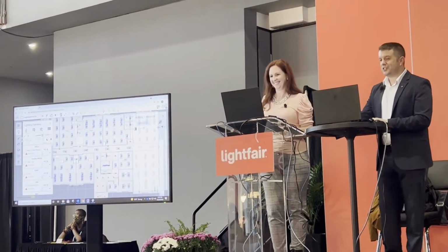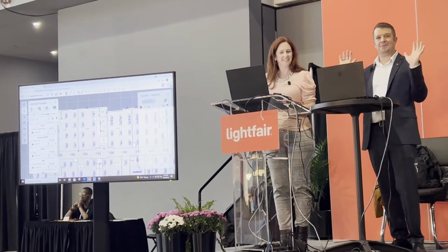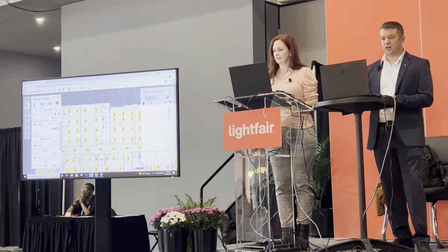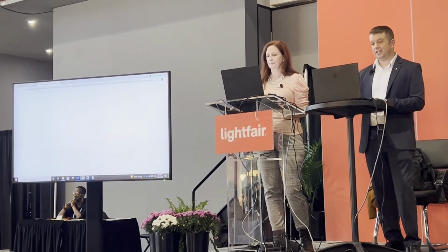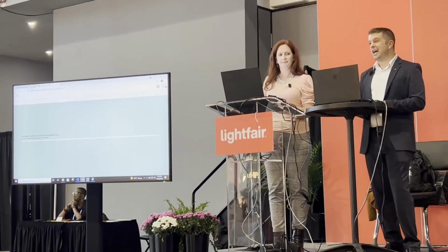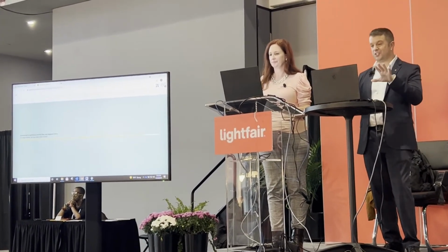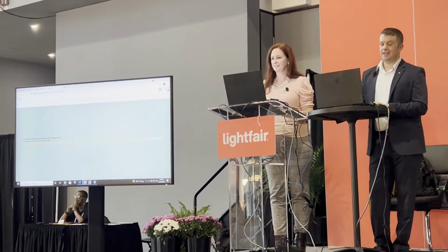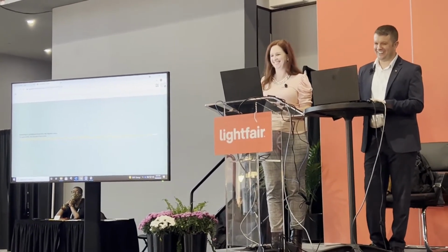So if you look at these light fixtures, they've got these red triangles. Those are saying, help me. I don't have an IES file. I came in from Revit, but I don't know who I am. So I can pick one of these light fixtures. It tells me no IES file. I click this here, upload new IES file. I pick one from my folder. Boom. So I think those fixtures now know who they are. And they are assigned. And I can go through and see which fixtures still have that until all of them are assigned. So I think this is the new upload. Yeah, this is a new upload, so it'll take a second.